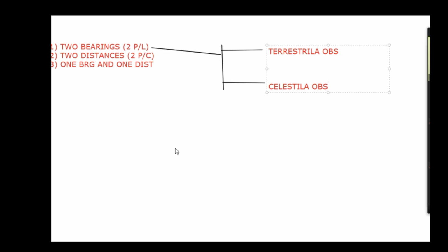Actually, this position line of the celestial bearing is not, in the true sense, a straight line. It is a part of a curved line, and the radius of the circle is your ZX, the zenith distance. The zenith distance sometimes is 30 degrees, 40 degrees; 30 degrees is 1800 miles radius. So it is a huge circle, a small part is considered a straight line, but it is actually a curved line, and we draw a line.